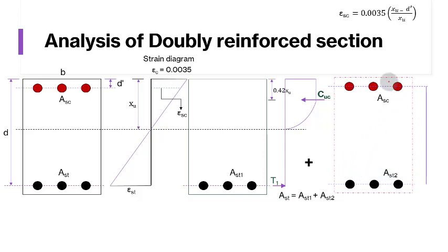Next we'll come to this diagram. Here we have compression steel. In this compression steel, we'll have the ultimate compression force in the steel which is located in the compression zone, whereas here the tensile steel is subjected to T2 tensile force because of the ultimate load. Now, if I want to know the total compressive force acting above the neutral axis, it will be the sum of CUC, the ultimate compressive force for a singly reinforced section, plus CUS, the ultimate compression force in compression steel.